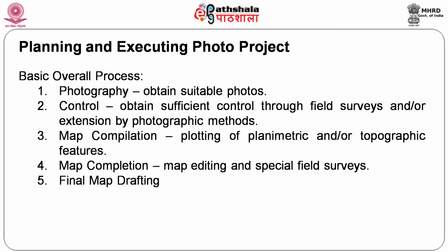Then of course, obviously after taking photographs, we try to compile the data. Either it could be planimetric in nature, 2-dimensional, or it could be topographic, 3-dimensional in nature. Obviously, we will also have options for compiling the data, editing it, and also a special survey method. And finally, we go for drafting of the map. So, the aim, you can see, is to plan the photography, take the photographs with control points, and then perform whatever is required in terms of correcting it, identify the objects, find the required features on the aerial photograph,